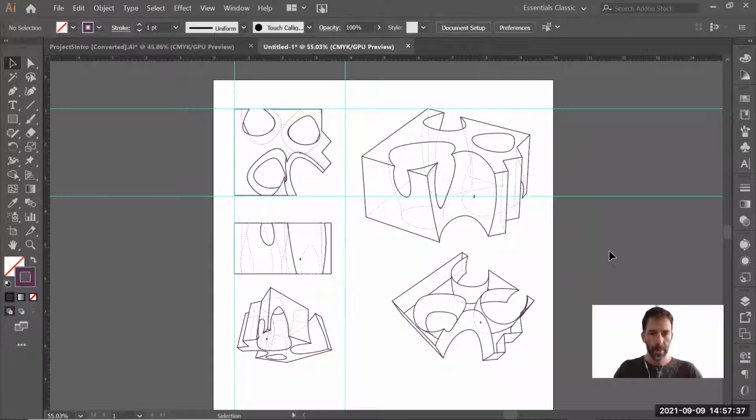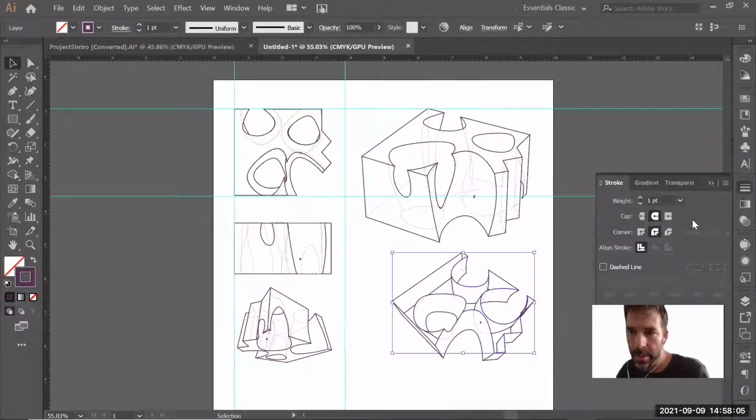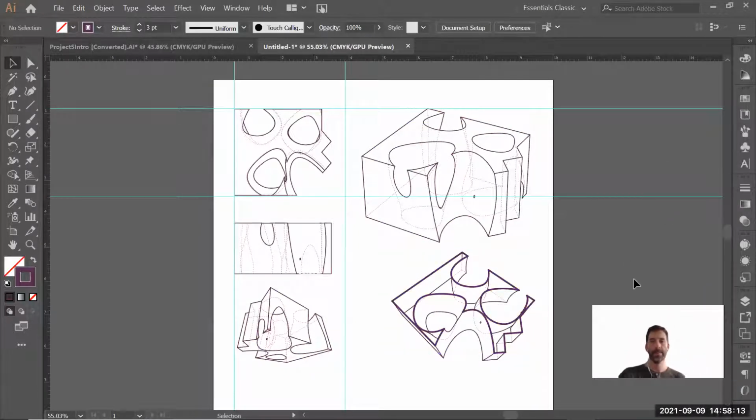Okay, so let's say this is perfect, which is not, because the bottom is a little bit too big compared to the top anyway. But let's just imagine I have gone through the process of creating the guidelines and that things are snapping properly to their place. There's one thing I'm missing, which is the cut from the section. So I can go to my section visible lines. Here is select, and that could be just to exaggerate a little bit thicker, like 3, say. So that's a way to show that section.